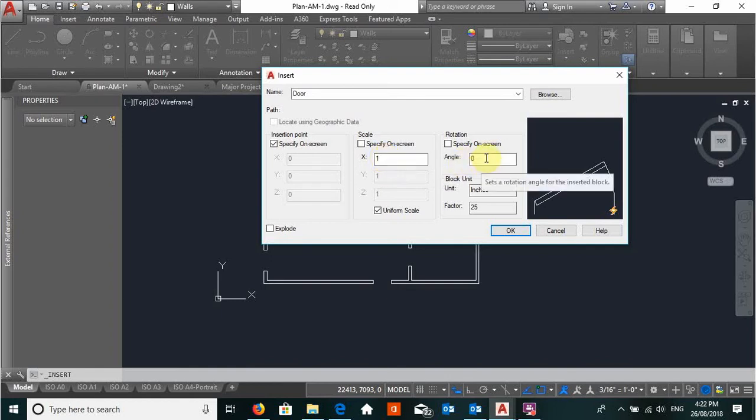We can also change the angle here, so we can do that by making it go in at whatever angle, 90 degrees, so that will flip this to lie vertical. Okay. This block was produced in inches. That's totally fine. It gets converted into whatever your AutoCAD is set up in, and of course that is metric, so in millimeters. So we just leave that for now.